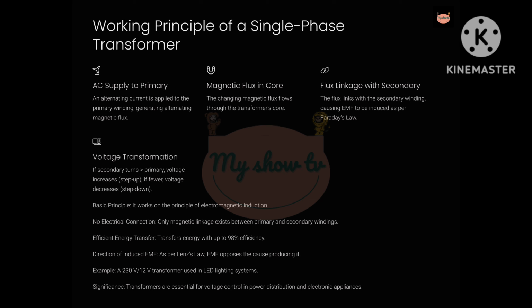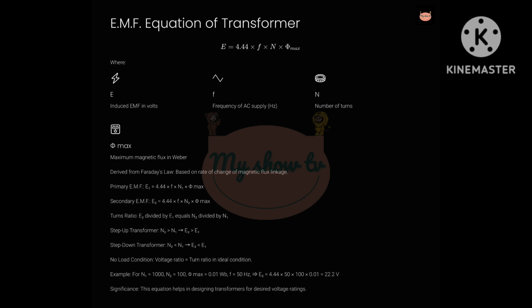8. The direction of the induced e.m.f is governed by Lenz's law, which states that the induced e.m.f will oppose the change in magnetic flux that caused it. 9. Example, your laptop adapter uses this principle to deliver the appropriate voltage safely from the wall socket. Slide 3. e.m.f. Equation of transformer.